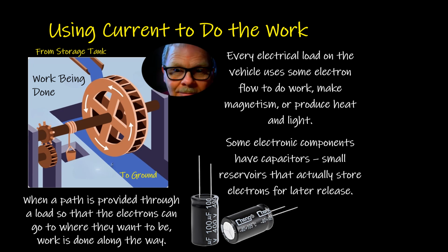Now, if you've got these great big ones, like you see in air conditioning units, those are big old capacitors, and they'll knock your hand off, so don't play with this stuff. But these little capacitors are going to be in these modules, and whenever you first hook the battery up, those capacitors, a whole bunch of them in a whole bunch of different modules, have to charge up, and it takes a while for that to happen. So that's going to show up as a battery drain that's only temporary, and that's normal.